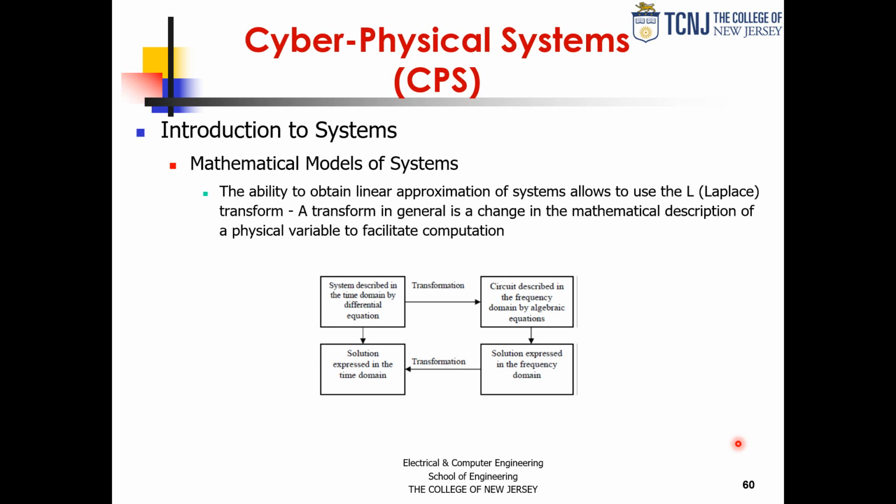Filtering is very easy to do in the frequency domain for discrete time systems. For example, you can get very accurate filters. For example, a digital filter with a very sharp response, meaning that you are isolating a very narrow range of the spectrum, so that outside that band, you're going quickly down by hundreds of dBs.